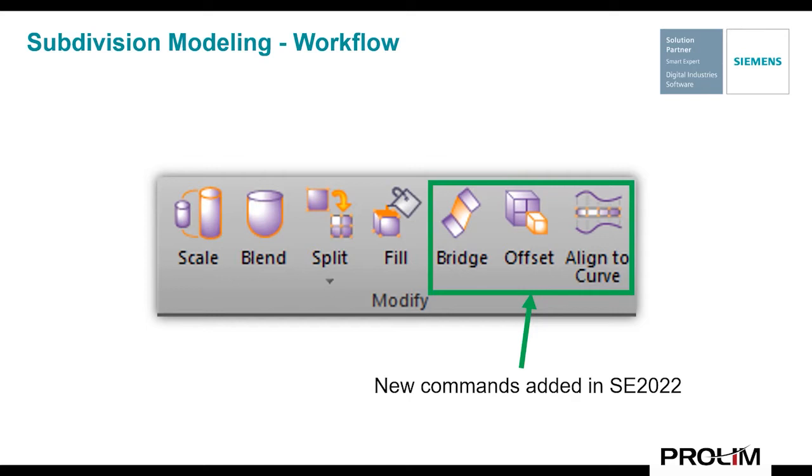You can use the Blend command slider to control how much selected vertices, edges, or faces pull on the body shapes, providing control over the curvature of the model around the cage elements. You can also use the Split command to add subdivision faces or faces along an edge across a selected face. Use the Fill command to repair a shape by creating a missing face across a connected edge.